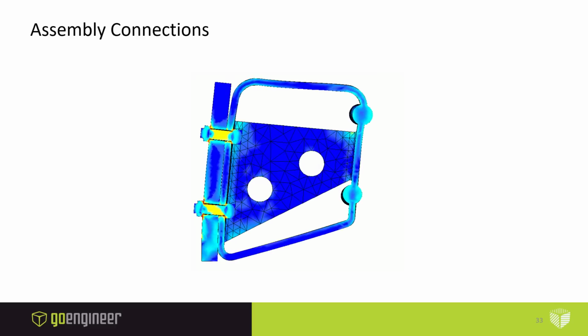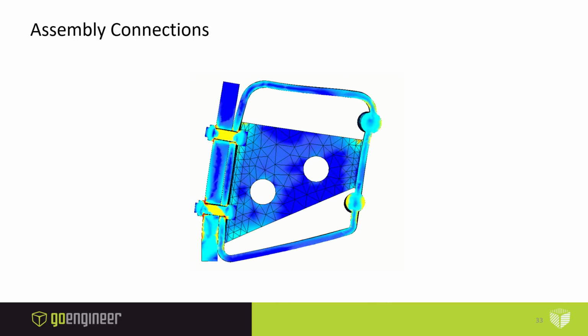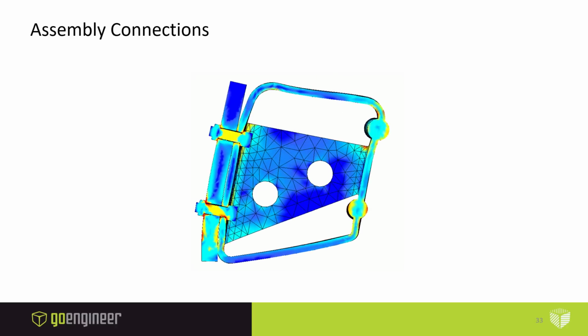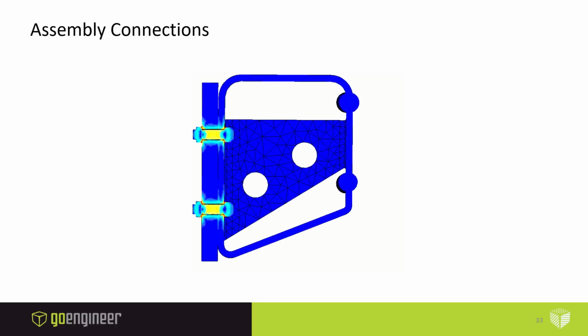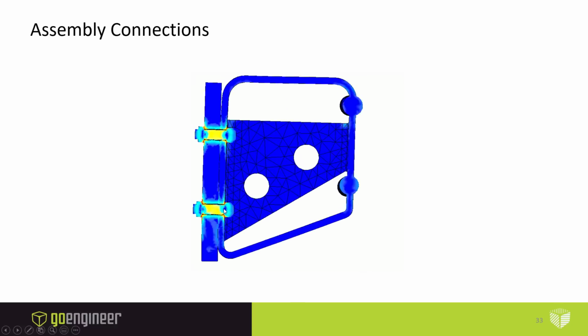But here's another result, if I actually model the bolts, which is something I wouldn't really recommend, especially for new users, in a static study. This can take hours to run, this level of analysis where you're physically modeling the bolts and applying friction and contact and all that.